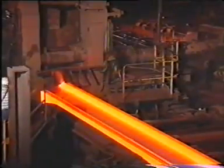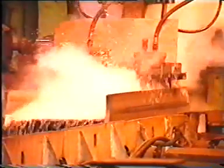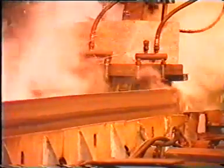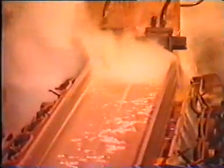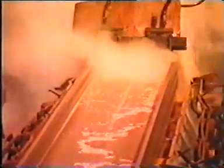Rolled sections are usual for rail bearers and stringers. Cross girders are sometimes rolled, sometimes welded. The main girder is usually welded. Connections can either be welded or carried out using high-strength friction grip bolts.